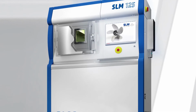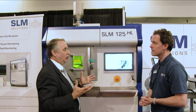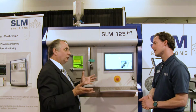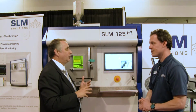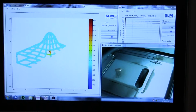One of the advantages of laser sintering based metal additive manufacturing, of course, is you can make wildly exotic and complex structures. You make structures that you couldn't even dream of doing subtractively. The disadvantage, of course, is that means you can make complex structures, which means it's harder to analyze where the stresses are, either residual stresses or functional stresses at that point. So tell me, if you can see it while you build it, does that help you troubleshoot if you mess it up? It certainly does.